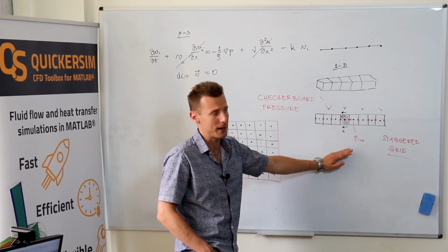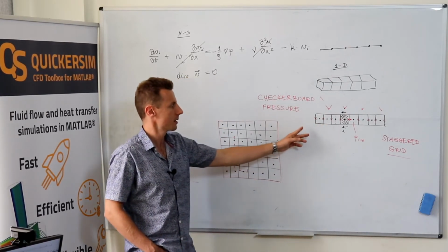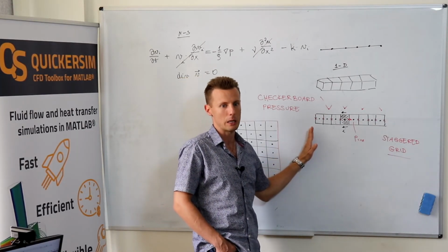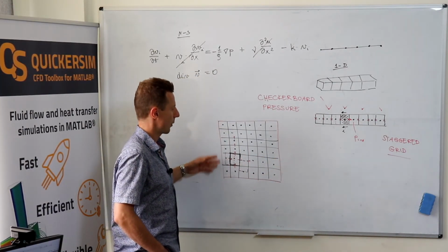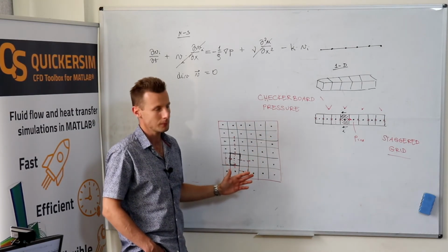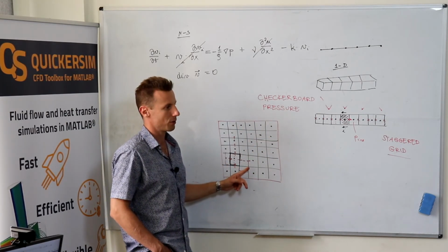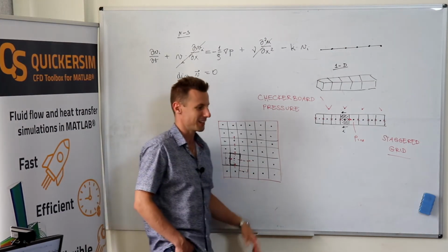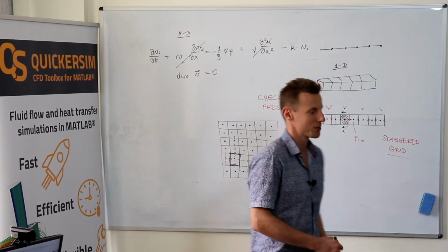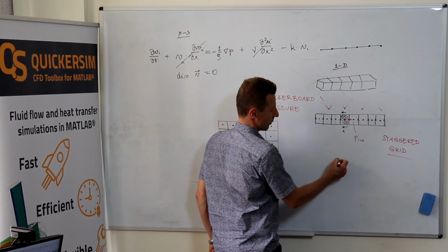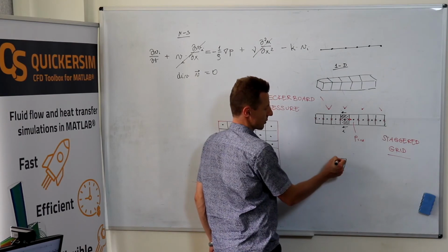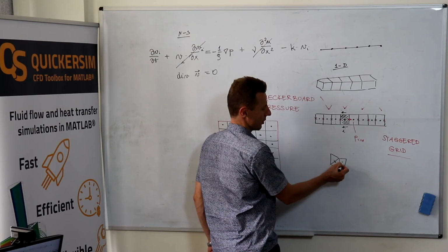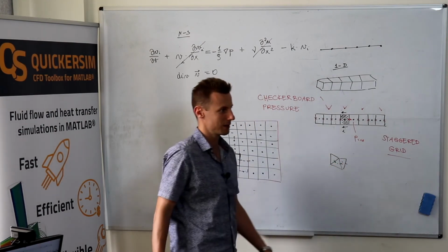Yes, because the staggered grid approach is very nice if you're dealing with very structured geometries. If you want to implement finite volumes on unstructured meshes, it's really difficult to imagine dealing with triangles, storing pressure somewhere, and x and y velocities, so how should you do that?